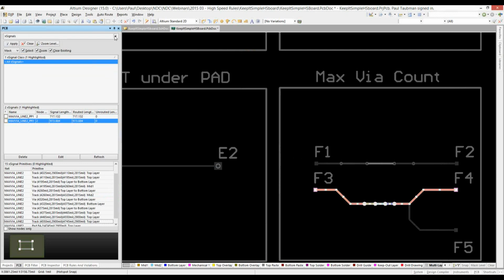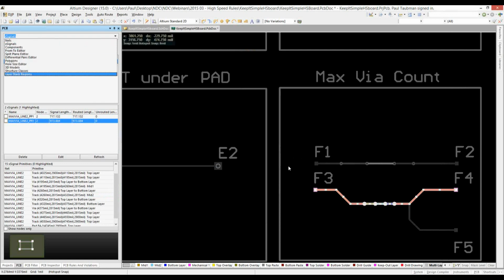You can also do this, by the way, in the nets as well. You can click on each of the individual components, on each of the individual pads. You can right-click once you've got two of the pads connected, and say, okay, I want these two to match up. Once you've got this over here, you can actually create a rule here.